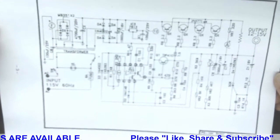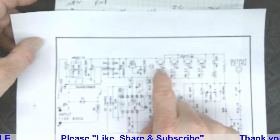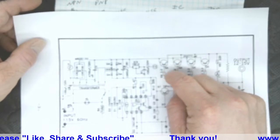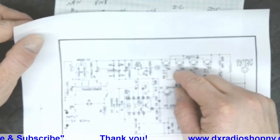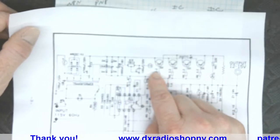So when you read a schematic, you'll know exactly, okay, hey, I got something wrong with this. I don't have the voltage. What is that? Oh, that's a transistor. I remember now. Okay, now I got to find out what caused the transistor to fail. Or is something pulling that transistor down? Is it a switching transistor? Is it used as a regulator? Is it used for what purpose? So now you got to identify all of that as well, which is later down the road. But at least you can identify a symbol, so you know what you're looking for.